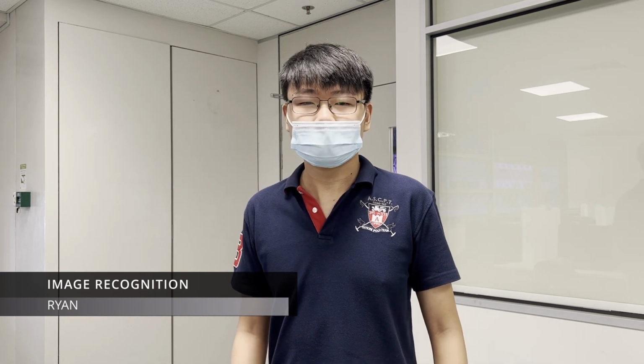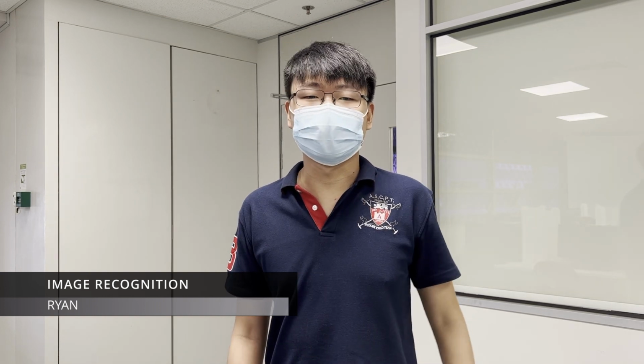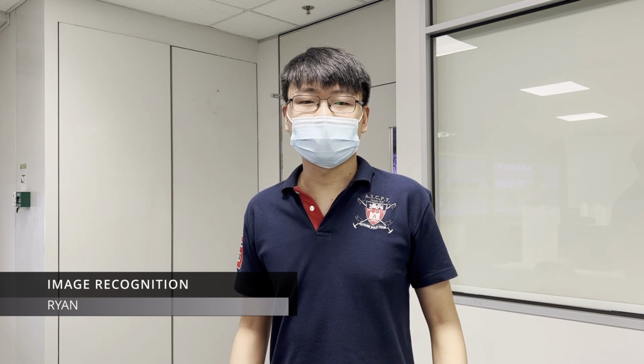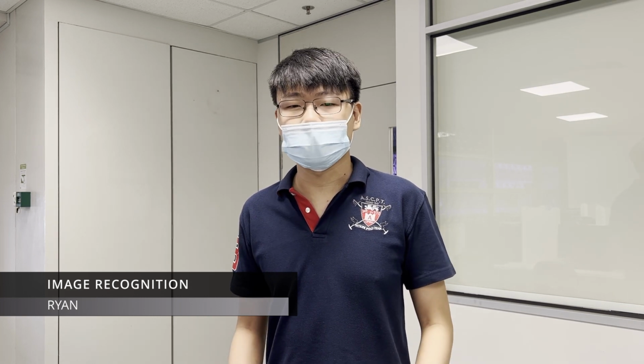Hi, I'm in charge of image recognition, which makes use of a custom YOLO V5 model trained to recognize symbols with a dataset of 3,500 images augmented to account for lighting and motion blur. An image processing server is used to receive images from the RPi and to process the images using the trained model. The inference results are then processed, comparing vertical bounding box height to find the symbol closest to the camera, and then outputting an image with the bounding box of the detected result.